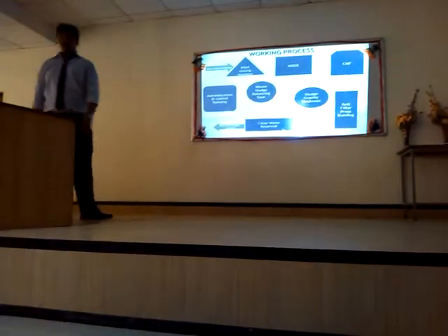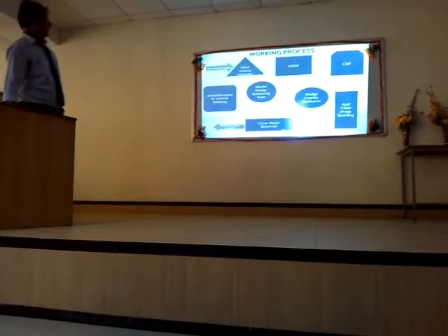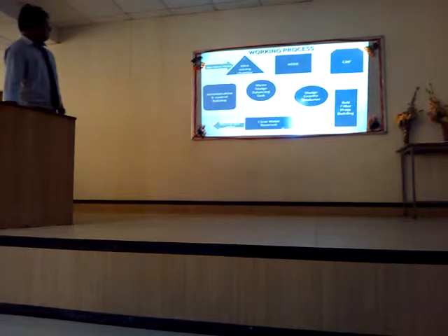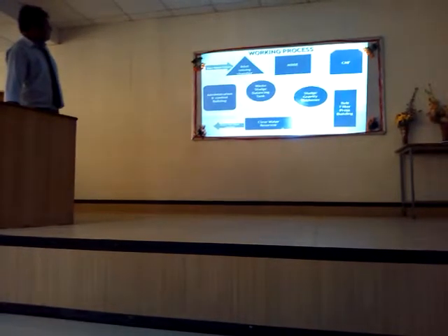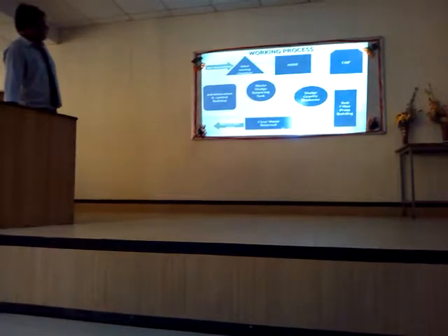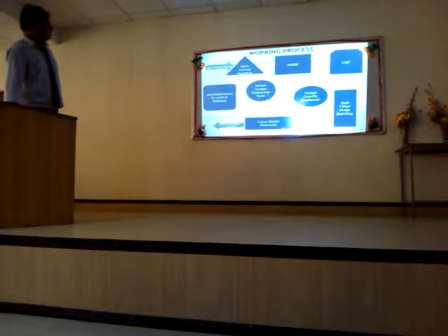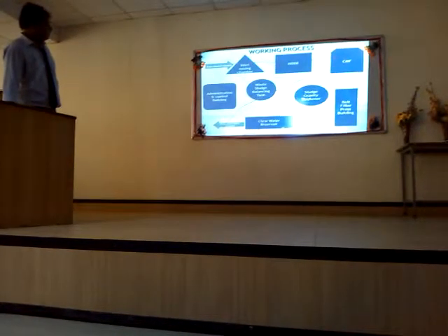Now the last portion of the section is the execution section. Here you see the whole process of this advanced treatment plant. See, the raw water comes from this. The water is sent to the MBBR. Then after the MBBR, the water gets purified and is sent to the CMF. After continuous membrane filtration, the water comes directly to the closed water reservoir.